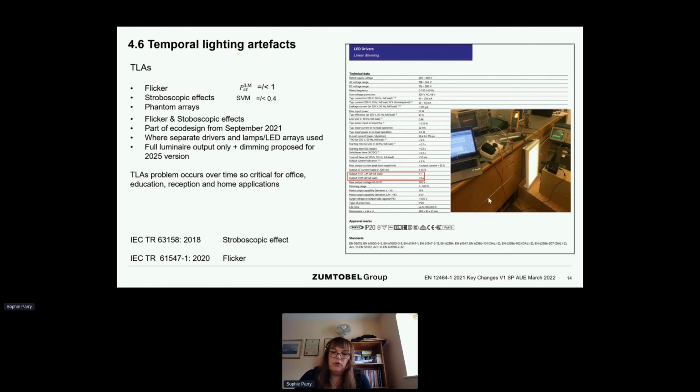And we're also monitoring the mains with the oscilloscope for any noise coming in from outside that we may need to take into account. So this is really the way to do it. It should be done through careful engineering design of the driver, and also the luminaire can be tested, or if you look at the driver data sheet, you're 99% certain that you're where you need to be with your specification.